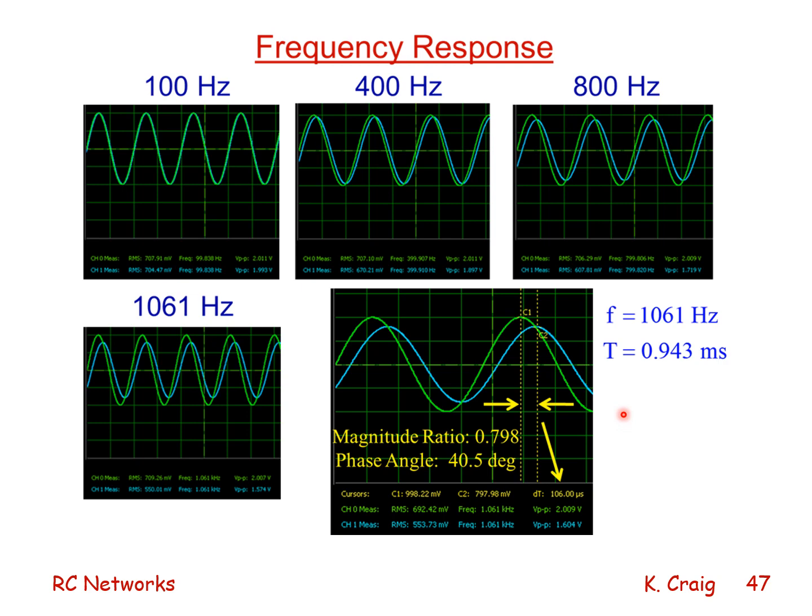Either in making these measurements, I changed the values of R and C, so 1061 hertz is not the actual bandwidth, and comes from the nominal value, and the actual values of R and C might be slightly different than the ones I originally measured. In any case, it's the process, the procedure that's important, not the actual values here that I'm presenting to you.